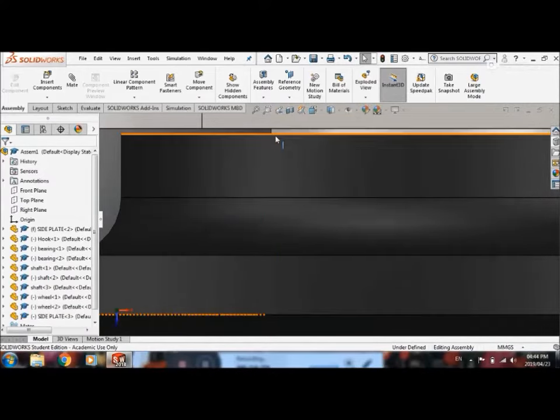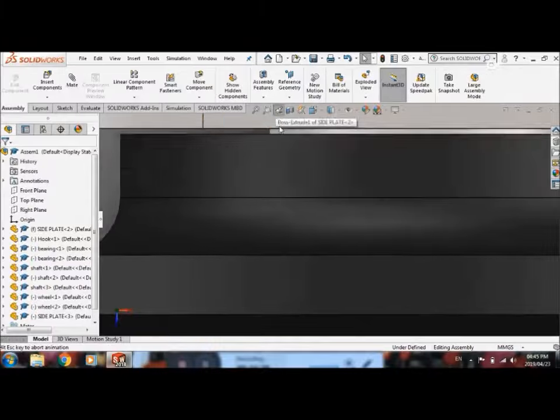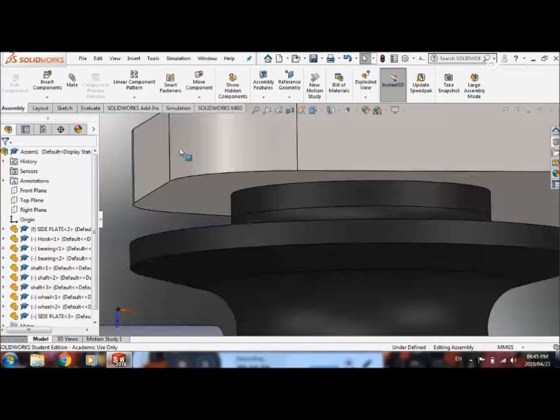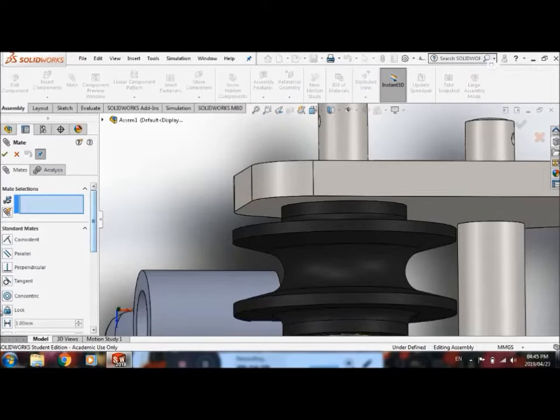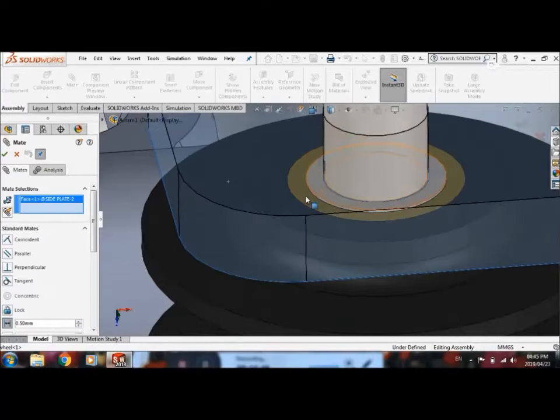Remember, I can't go and specify it on that side as well, because then it will over-constrain the assembly. Let's quickly do that, then you'll see what I mean. So let's do a mate of distance 0.5 from this plane to that one.